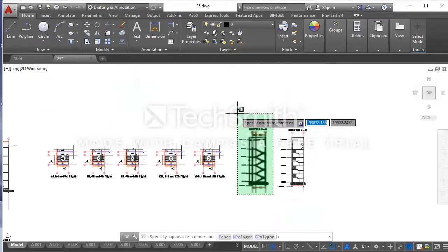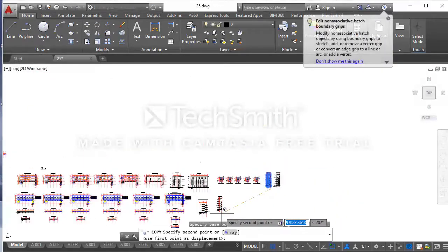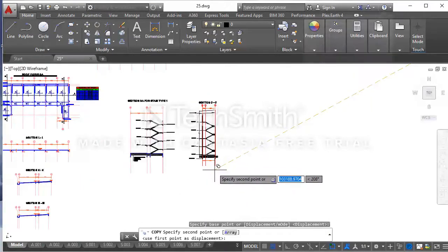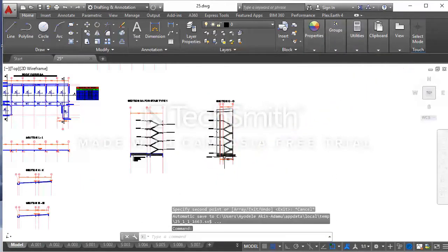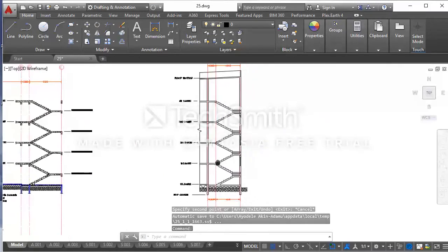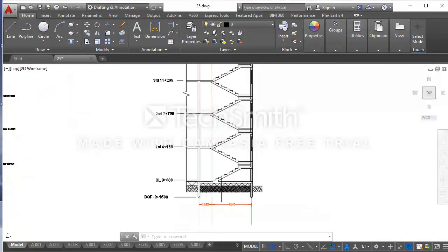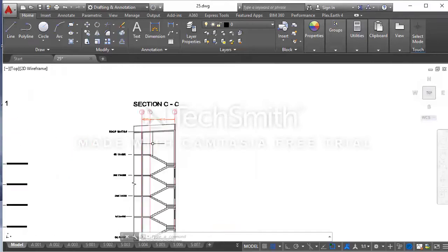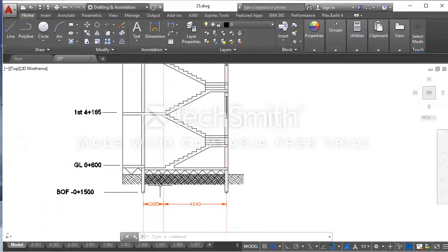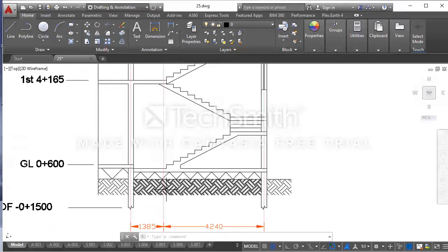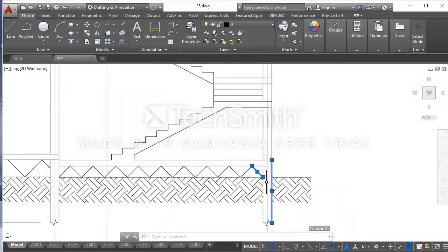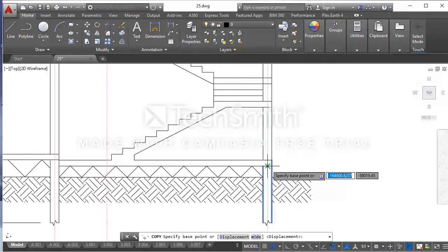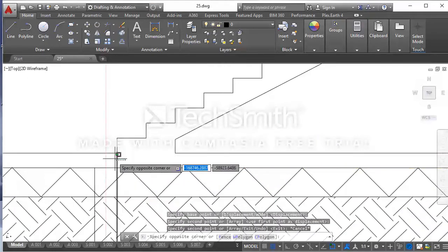So I'm going to select all these objects here, duplicate them at a point after our section GA for the stair type 1, and I'll make serious edits to this drawing instead of replicating the drawing from scratch. You will notice at the bottom at grid C, we don't have a structural wall, we don't have a foundation wall in our architectural drawing. I'm going to provide that quickly. I'll select these 2 lines that denote our foundation wall, and I will paste at this point.